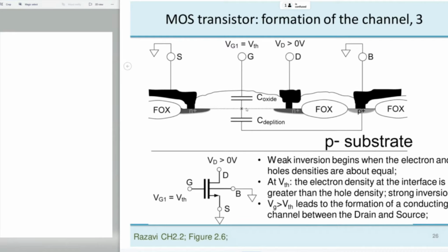We chased away the holes through positive voltage at the gate, and now the voltage is so positive at the semiconductor-oxide interface that we start collecting electrons from the source. A channel is created. The electrons which pile up at the interface will eventually extend all the way to the drain, and they'll create an area which behaves like an N-type semiconductor. We inverted the channel. There is inversion of the interface below the oxide.